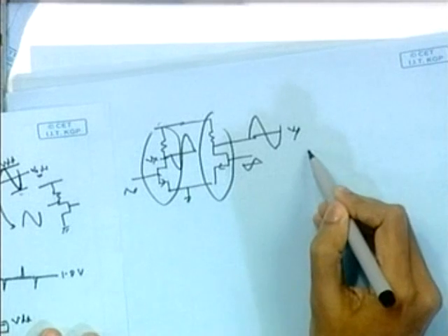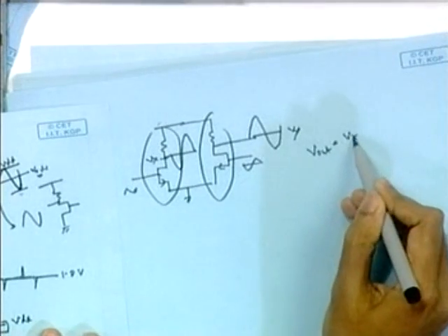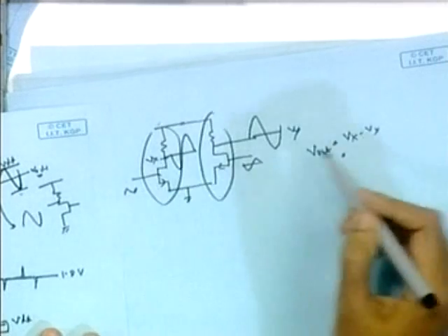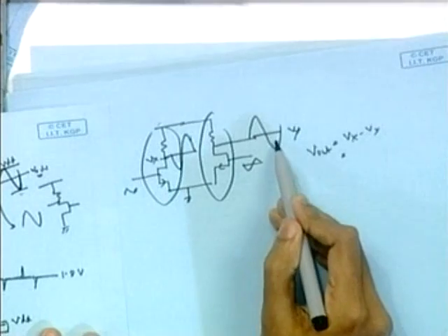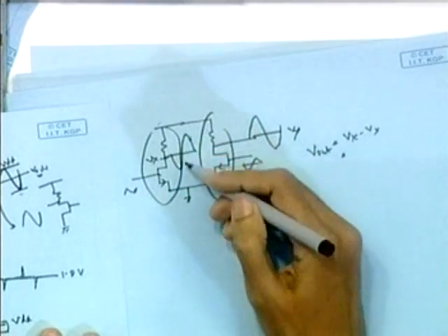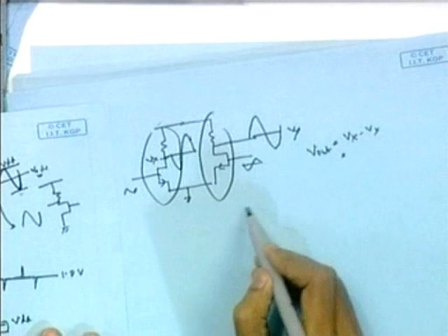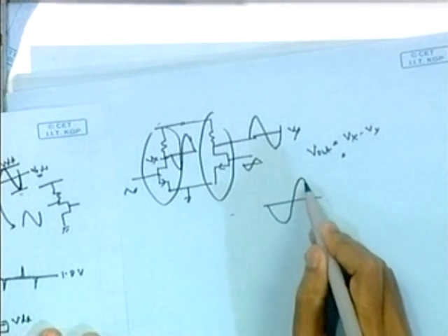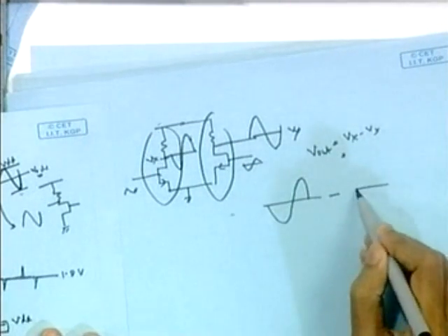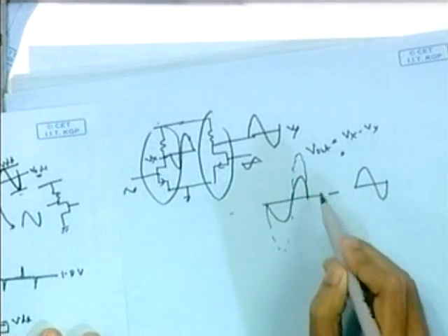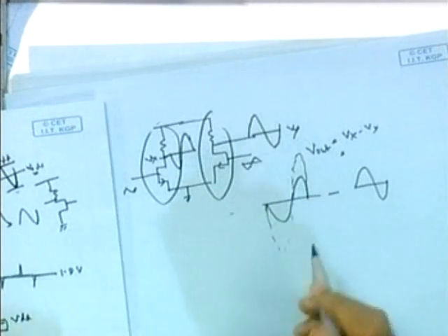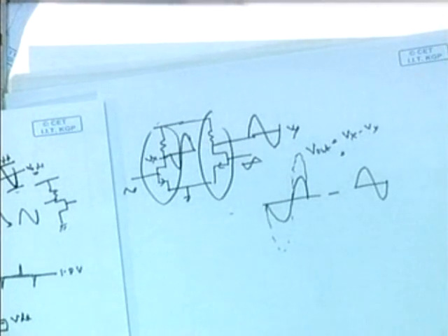This is Vy. Now we define our new V out as Vx minus Vy. So basically this waveform minus this, we are getting twice the swing it had previously. So our effective output swing increases. So these three are the main reasons why we are using differential amplifiers in our analog circuit design.